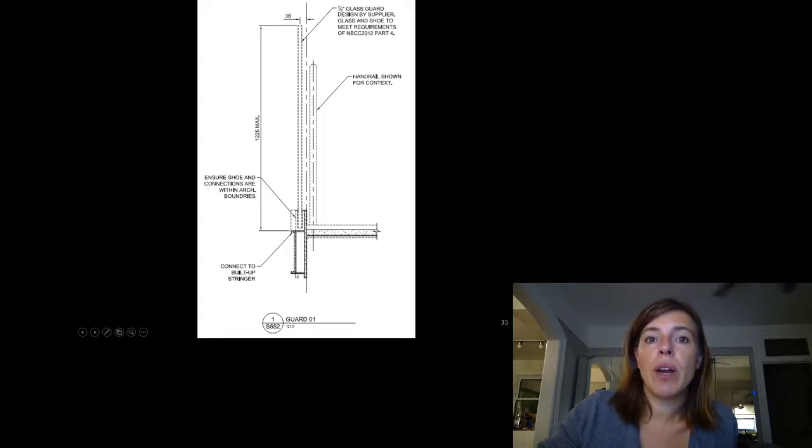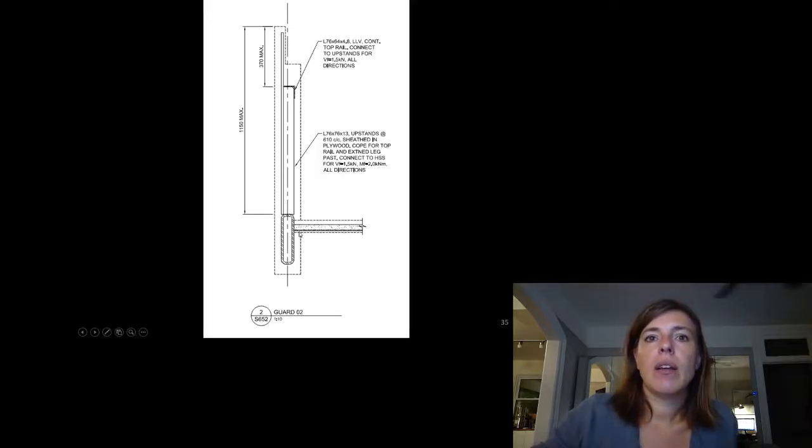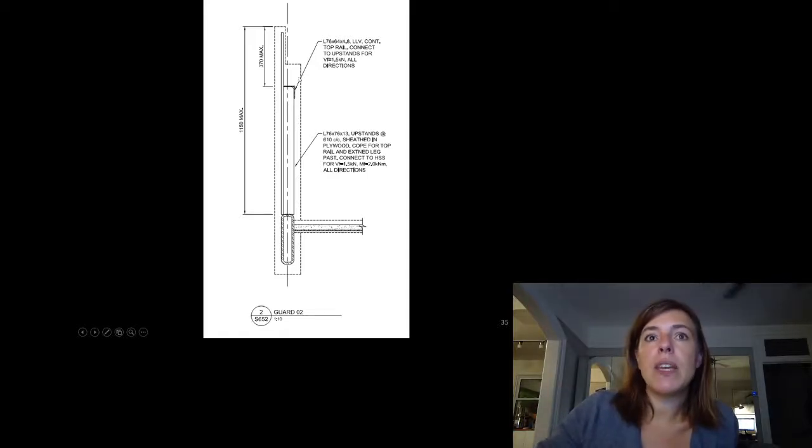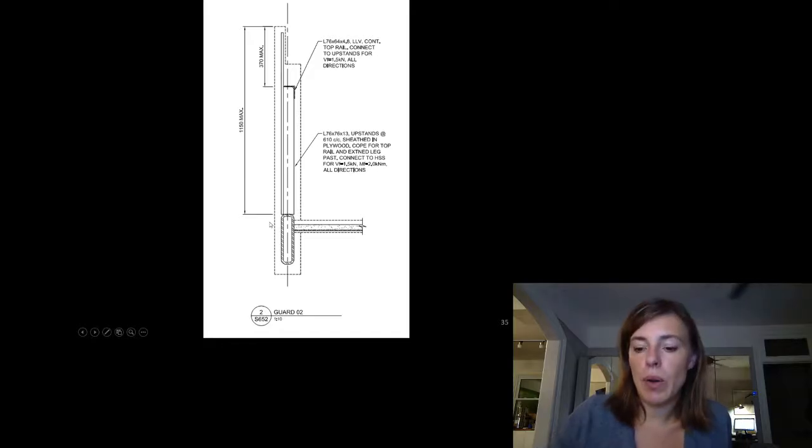This was the stringer of the stair, and this would get anchored down here. This is the inside stringer. So this was the one that was working harder, that had the big loads on it. Here's the HSS stringer. And then these were LVL upstands every couple feet with an angle on top, and then they built the rest up out of plywood.